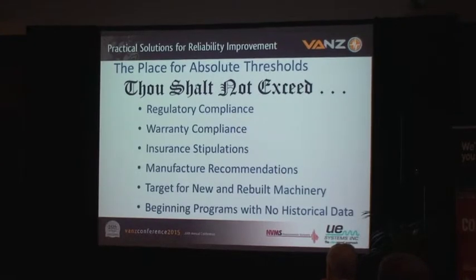Basically, when you have a situation where your machine has some level of regulatory compliance, or you may have a machine that's under warranty and the manufacturer or the supplier says, I will only warranty this machine if you make sure that the vibration stays below a certain level, then these are appropriate uses for a thou shalt not exceed criteria. Insurance requirements, too.